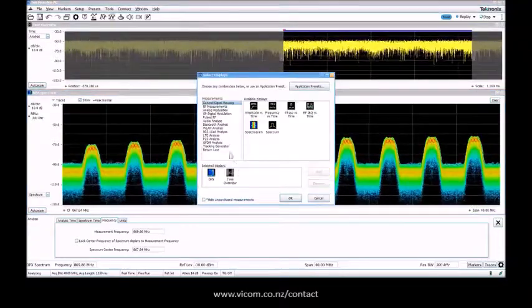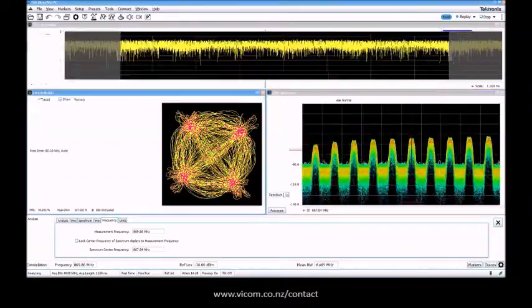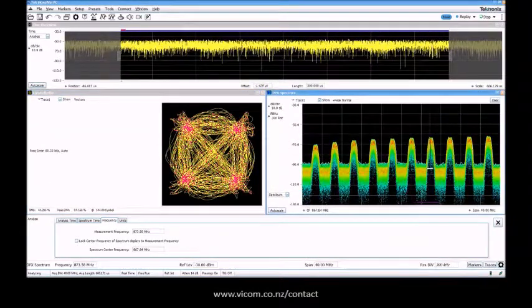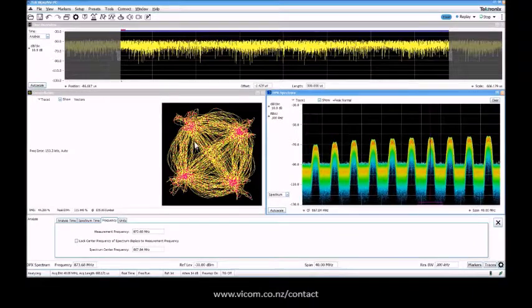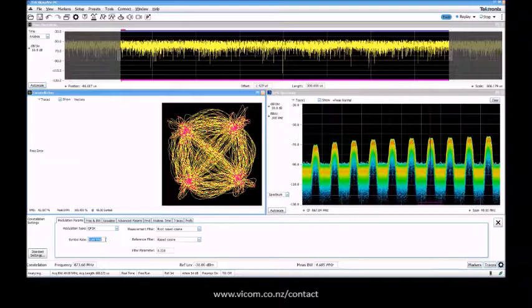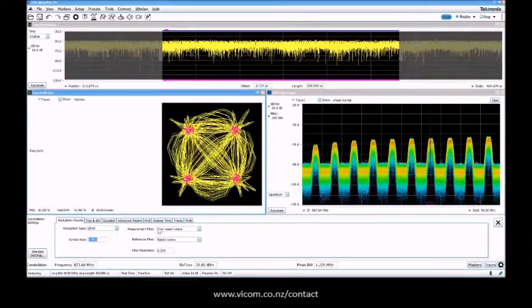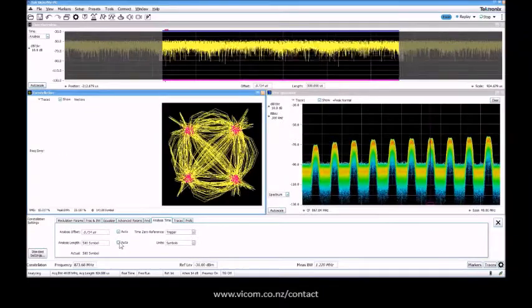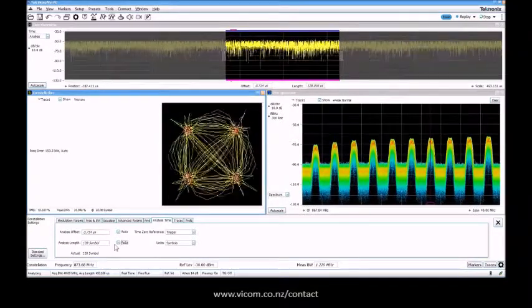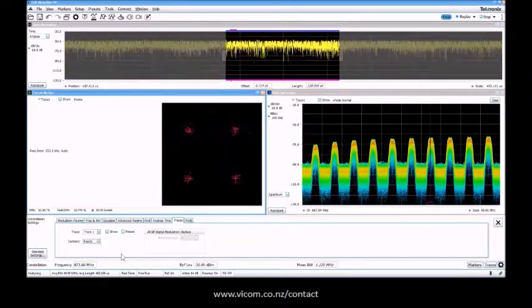And the third and last one I will go in is the general purpose modulation for the constellation. So let's try to do some tests here. So we have this one. We need to set this up. We had 1 megahertz. We'll put 1 megahertz. And we have QPSK. And we go for analysis time. We can go for 128 symbols or more. And we go for traces. And I want to see points. And this gives us an EVM.